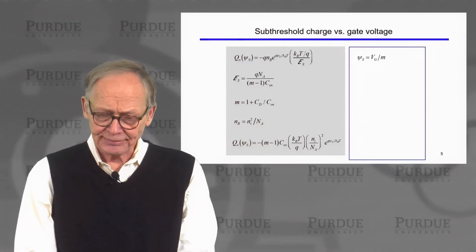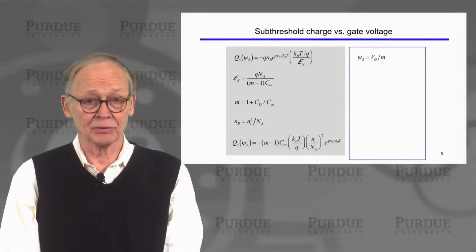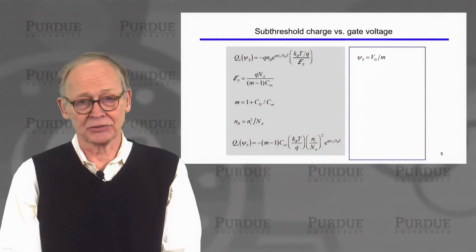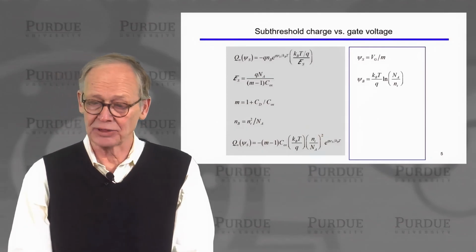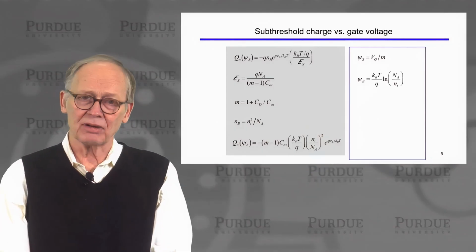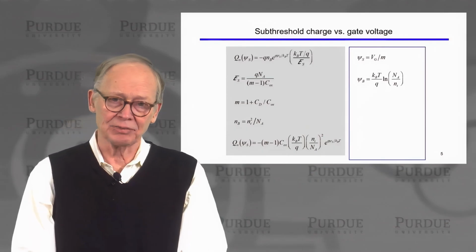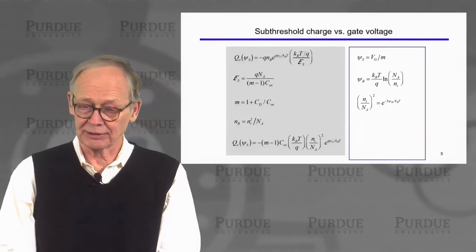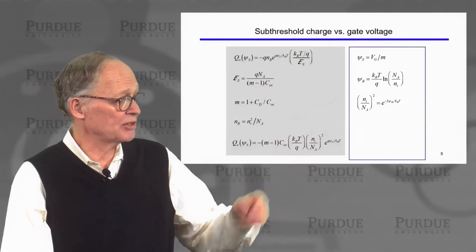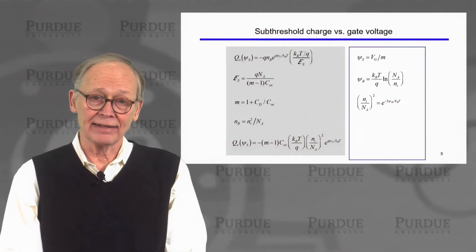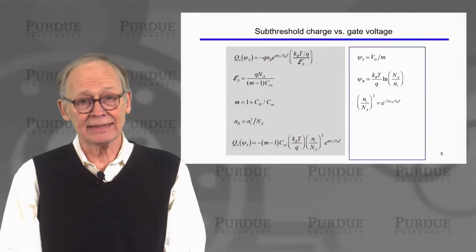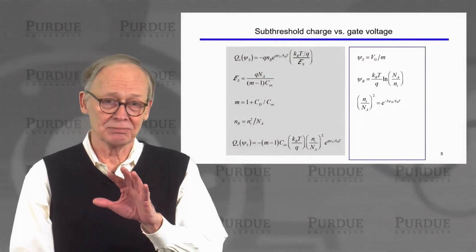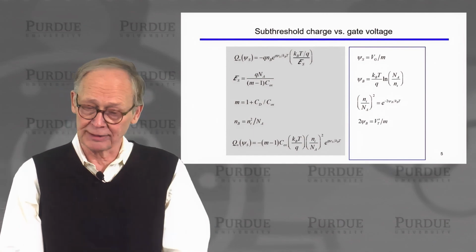Okay, now, we're trying to relate this to the gate voltage. We're using our approximate two-capacitor model to say that the surface potential is some fraction of the gate voltage. Also recall that this key parameter psi sub b, which tells us how much we have to bend the bands to invert the semiconductor, you can easily show from that relation that (Ni over Na) squared is e to the minus 2 psi b over kT. So stop and prove that to yourself if you don't see it immediately.